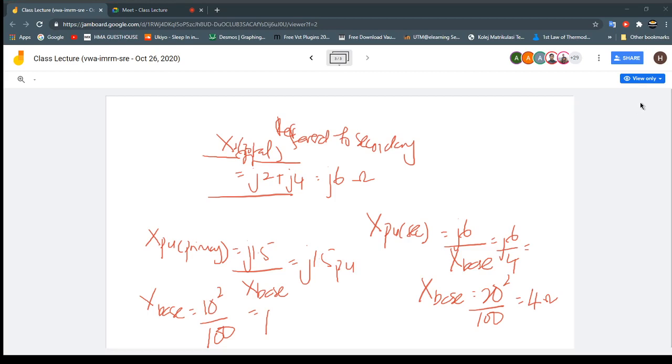So this is the nominal value, the voltage and the power. Then what we have done is to bring, you can see the primary and the secondary reactance. So in making the equivalent circuit, or in removing the coupling circuit, we have to bring this quantity to the primary or secondary. So let's say we refer to the primary first. I bring this secondary reactance to the primary by multiplying by the square of the turns ratio. So 2 times the square of the turns ratio, 10/20 squared, I get j0.5 ohm.